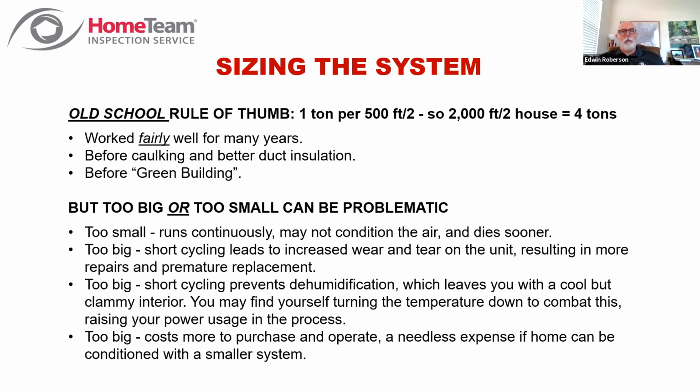That extra humidity in the air: two things. One, you're going to keep bumping the thermostat further down because you're just not comfortable, raising your power usage. But that humidity is also going to do things throughout the house that you don't want to happen. So if you ever walk into a house and it feels cool, but there's just something that feels wrong, start asking questions about sizing of the system.